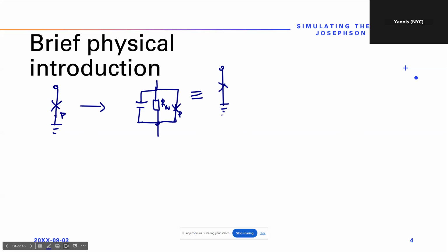And in our situation, we add to this real Josephson junction another resistor. So we build something like this. We have a real Josephson junction and a resistance here. We call it RS, like shunting resistance, because we want to be able to modulate this voltage response by changing this resistance.